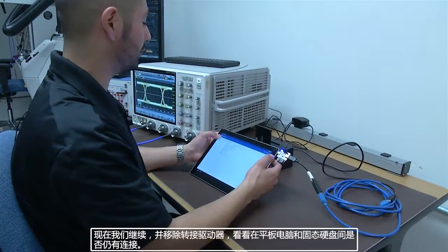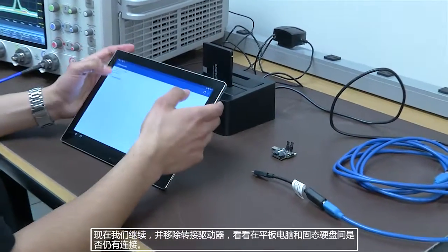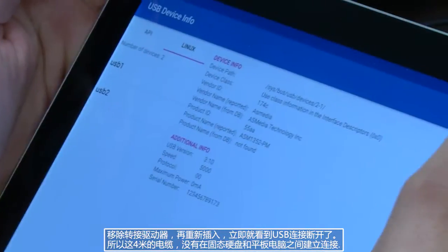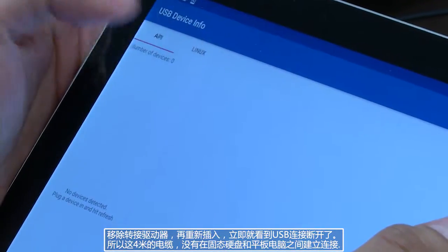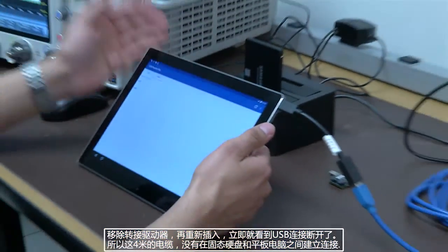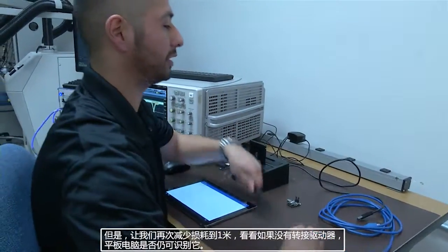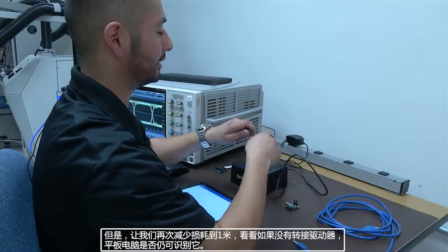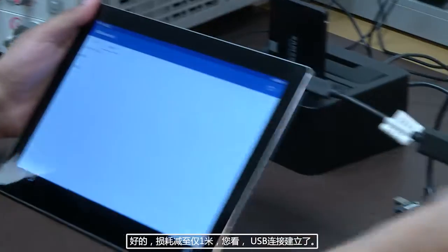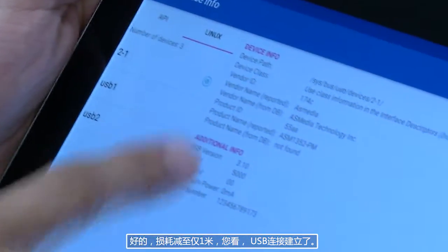Now let's go ahead and remove the redriver to see if there's still a connection between the tablet and the solid-state drive. So the redriver was removed, plug that back in, and immediately you see that the USB connection was dropped. So with this 4 meters of cable, there is no established link between the solid-state drive and the tablet. But let's reduce the losses once more to 1 meter to see if the tablet can still recognize it without a redriver. Okay, shorten the amount of losses to just 1 meter, and there you go, a USB connection was established.